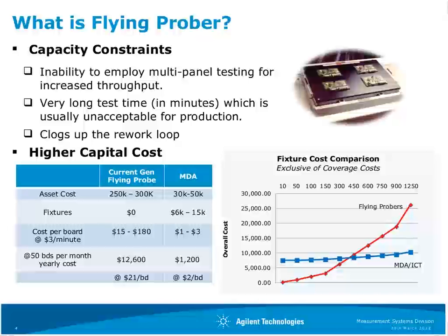But we've seen very often that some customers are questioning the use of flying probe. And we see the coverage and capability of flying probe can be overstated. Arguments and studies exist that now challenge the utilization of flying probe and question if it really is an effective means to capture defects. On the slide shown above, it demonstrates that from studies and from customer feedback that we've received, at volumes of around 250 to 300 PCBs per year, the cost of a flying probe is negated by the cost of buying a low-end fixture.